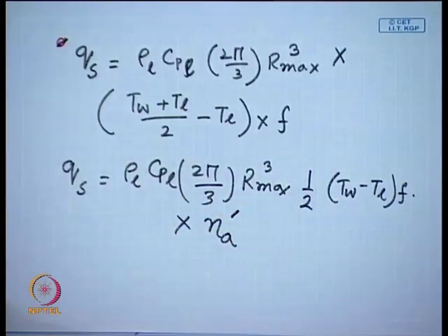What happens? As the degree of subcooling increases, as the liquid bulk is more subcooled, we will have the departure diameter of the bubble smaller and smaller. This experience we are having in any case of boiling. So, even if you heat oil or heat water over a pan, you will find that when it is subcooled, the bubbles are leaving the heated pan surface at a smaller diameter.